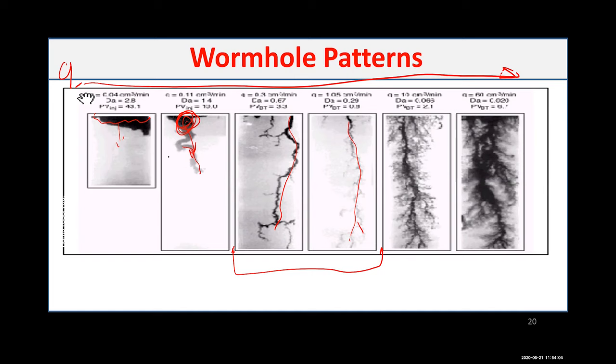At a lower rate, you will have the face dissolution and you will also have a well integrity issue, so you don't want to have this type of scenario. If your rate becomes extremely high, you will see what we call branching. You'll get a main wormhole, but away from it, you'll have a lot of branching happening. But this is not happening so often. So a lot of the time we will recommend or design based on the optimum wormhole.